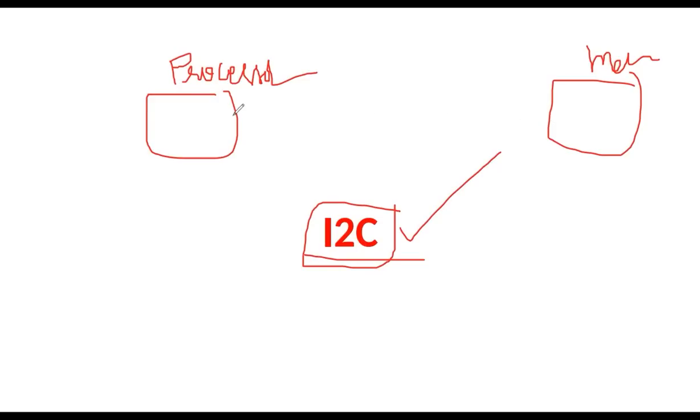Mainly, what is the size of the processor and what is the memory of the processor. Suppose it accepts 128 bit, meaning how much size it will accept, either 64 bit or 128 bit. That size you need to observe first of all. Then what is the communication process, either serial communication or parallel communication. That is one point you need to take. And is it half duplex or full duplex? Mostly protocols will be half duplex only. Half duplex means write and read operations cannot be done at a time.